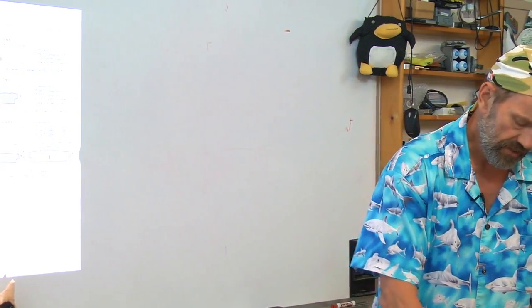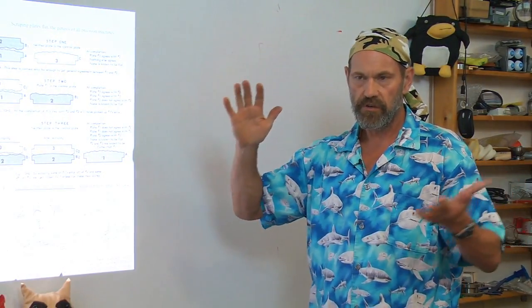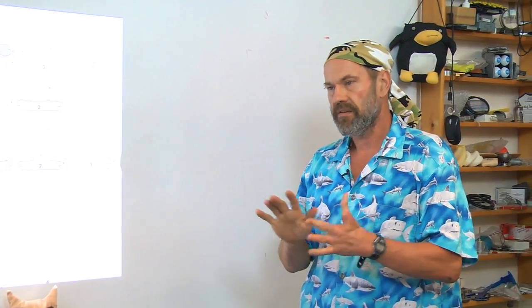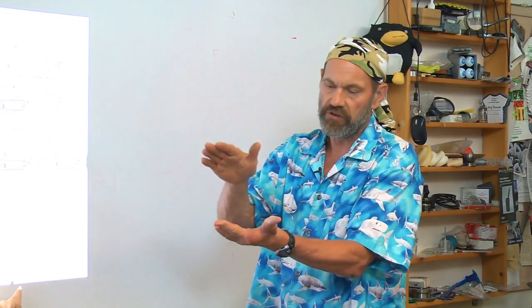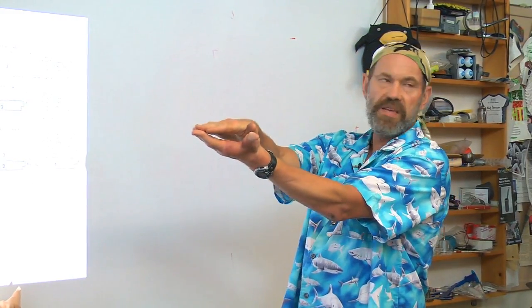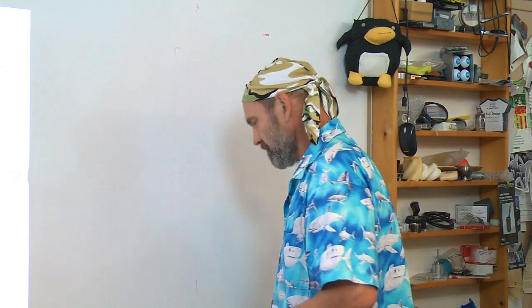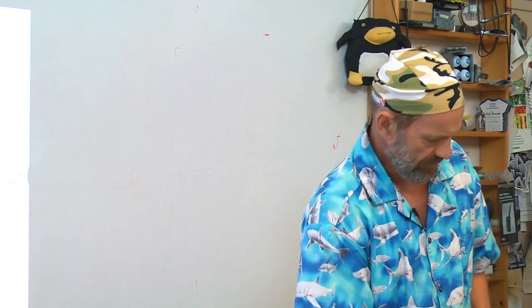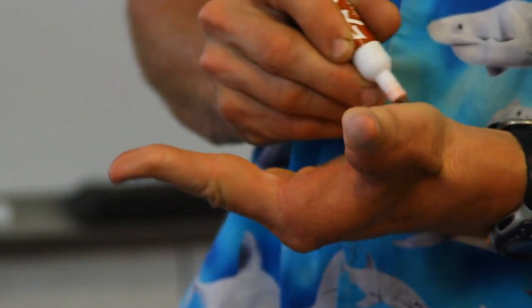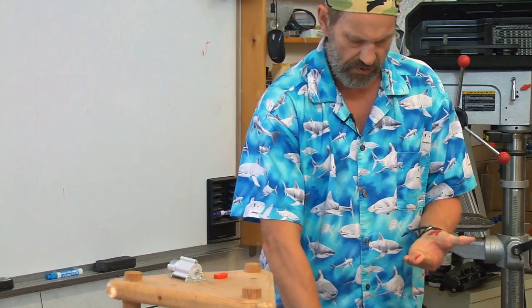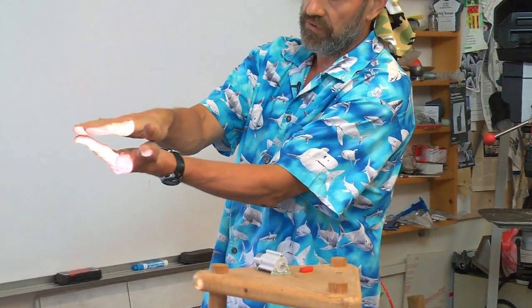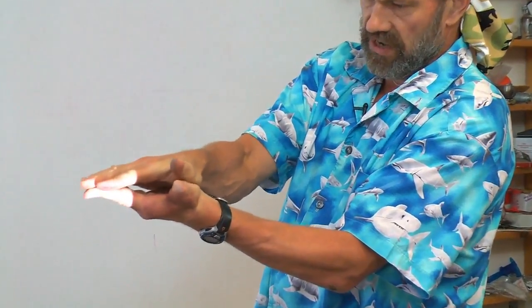Indeed, one of the ultimate forms of elastic averaging is scraping plates together. Large machines put together and bolted, you'll find that in the traditional ways of designing and manufacturing machines, you knew that when you brought the two surfaces together, there would be gaps between them. So you put a little bit of coloring on one. Let's see if I can do this real-time experiment here. If you put coloring on one against the other, when you brought the two surfaces together and touched and pushed, you get what's called rubbing a bearing.